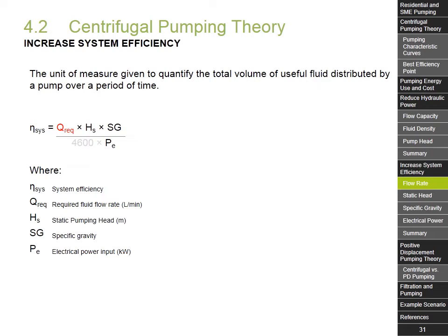Flow rate is equivalent to flow capacity, as covered previously. Rather than motor power, flow rate is generally the decisive factor in the sizing of a pump for installation. This is because pumps are generally installed to deliver product X by time Y. It simply isn't useful to have pumps that are oversized or undersized, though most err on the side of oversizing pumps for safety.